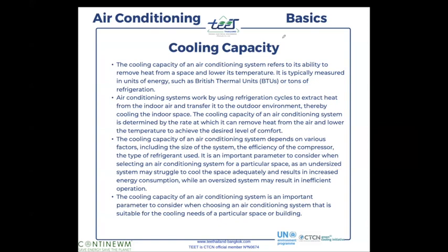We switched from 30% to 40%. But if the cooling capacity is too undersized, then we can cool better, but we cannot save energy. So that's why the cooling capacity is always very important to estimate. I will work on a specific guidance on that, because it is important.